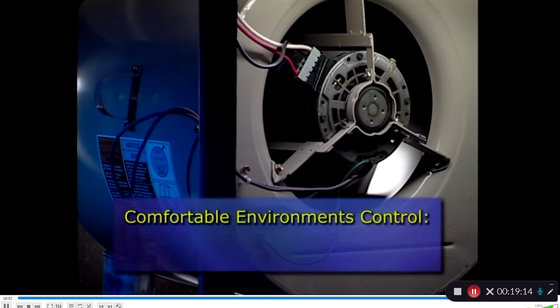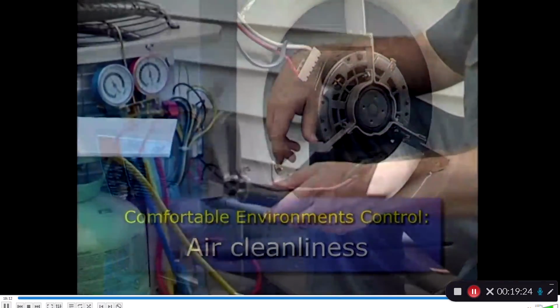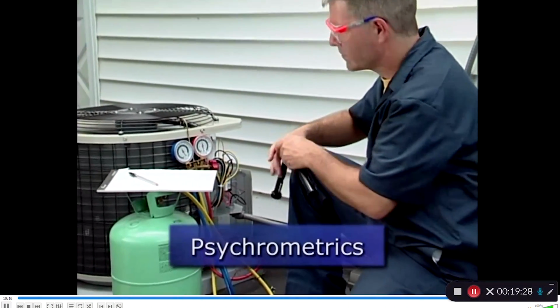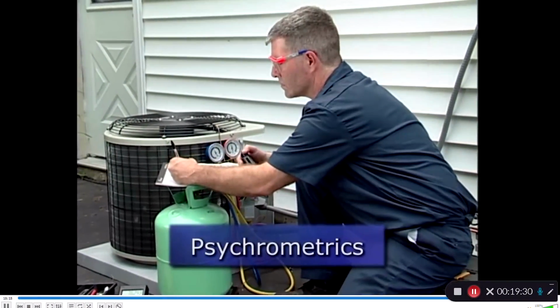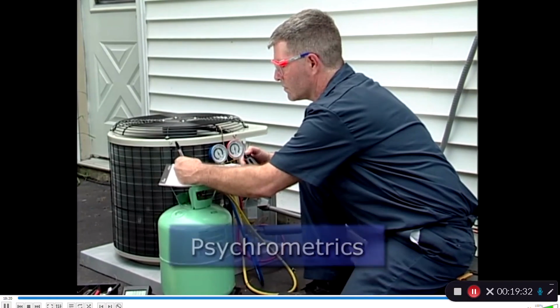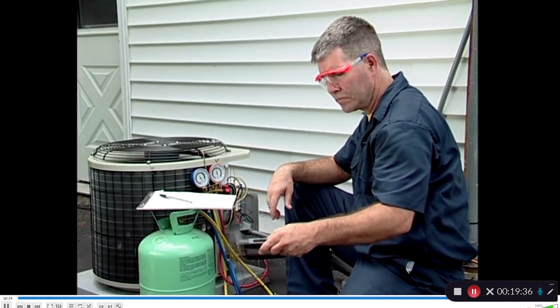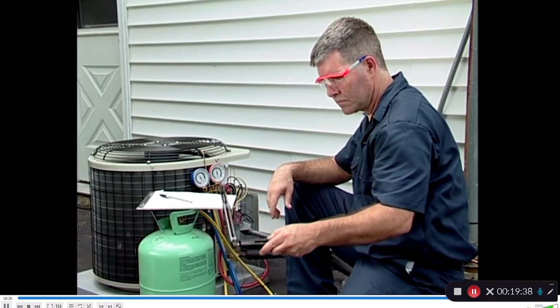Comfort can be achieved by maintaining and adjusting various factors in the space, such as temperature, humidity, air movement, and air cleanliness. The study of air and its properties is called psychrometrics. Common air properties include dry bulb temperature, wet bulb temperature, relative humidity, moisture contents, specific volume, and heat content.